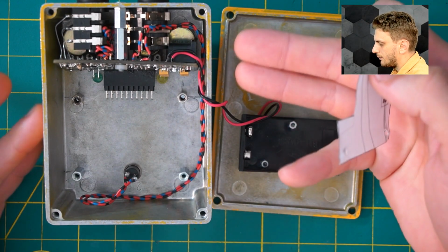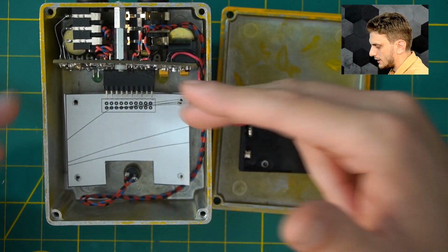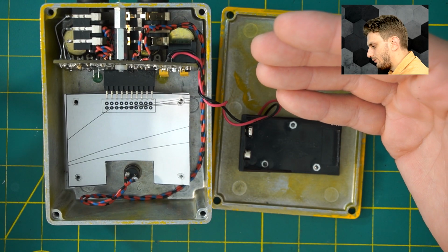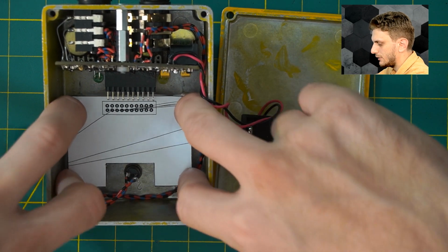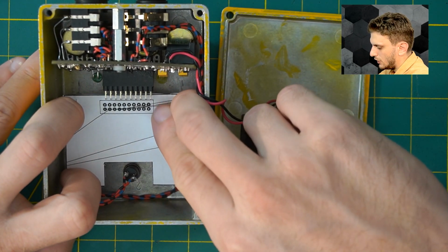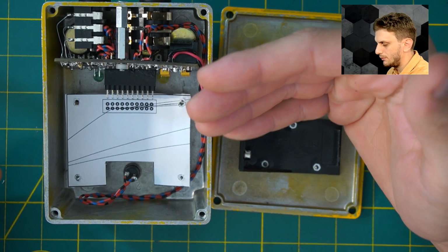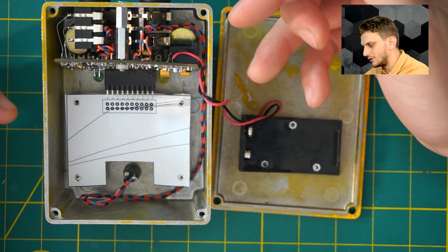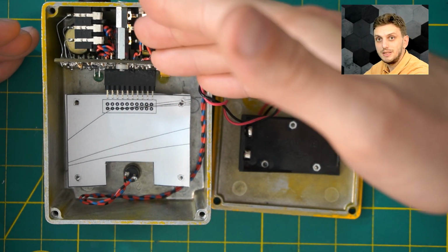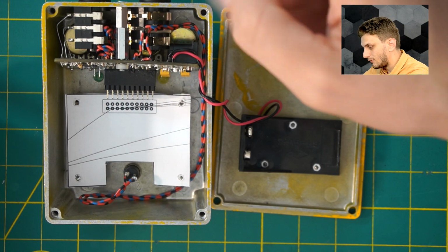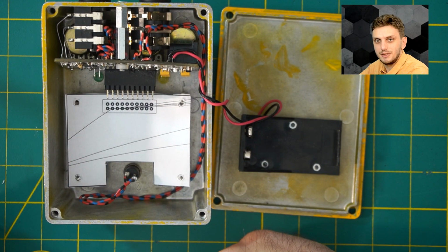Now, if we look at it in our final effect circuit and we try to put it in, we can see that it lines up with the spacers quite nicely, but it doesn't really line up with our interboard connector. So even if I tighten out the paper like this, we can see that we have an offset of about 1 centimeter. So there's two causes for this. First of all, our board is at an angle, so in our initial design the board was nice and perpendicular, but because of reasons really, the board is sitting at an angle, so that is pulling the connector a bit to the side. But it's also because of my estimation skills.